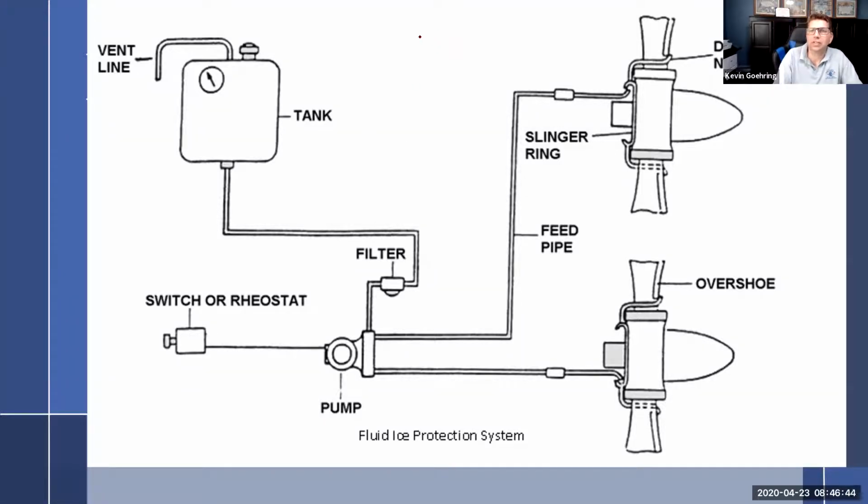So we'll just take that, enlarge it. We'll just put a little lump right there. I'll put a ball in here with the spring going to something. And so what happens is the fluid pressure has to build up to push the ball out of the way to get it around. Otherwise, if you had an open line all the way through the pump and the filter, you're going to have a negative pressure behind this propeller right here. And so that negative pressure would constantly be sucking right there and it would suck the fluid right out. And that would be a bad thing.